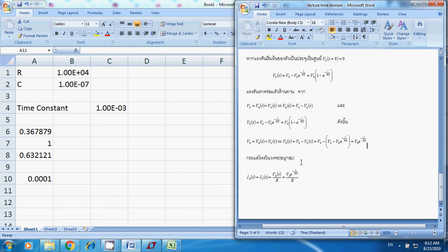This one is going to be more complicated because you are talking about second order circuits, because you have devices that depend on frequency. Here this means you have L and C, right? The frequency dependent. And then you need to analyze overdamped, critically damped, and underdamped. You can do the circuit in LTspice.